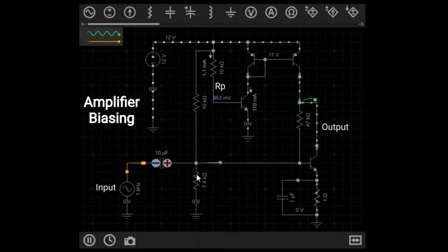By maintaining a constant current through the collector, you have an active rather than a passive load. This yields a very high voltage gain because an ideal current source has infinite resistance. The current mirror serves as this constant current source. This is a DC blocking capacitor.